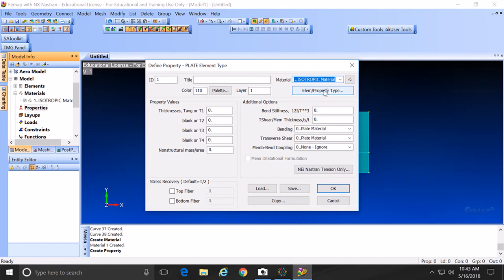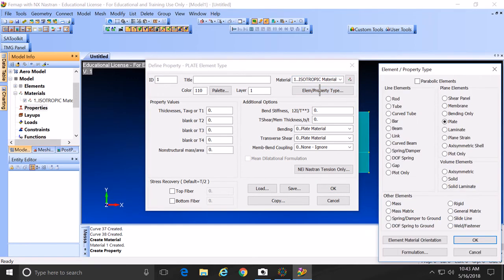Okay, so we go to stiffeners and flanges, you click element property type, and here you have a lot of elements. The assumption that is made is that each one of the members only carries loads in the axial direction. This is why it's called a one force member. So do beams carry forces in just one axial direction? No, beams can stretch, but they can also do what? Bend, no? Okay? So what is the option over here is to use a rod, and this would be the